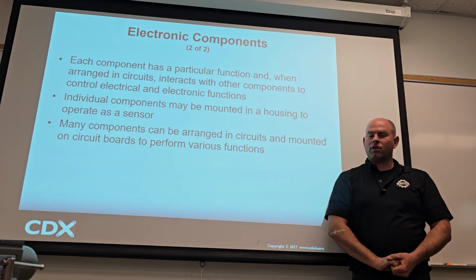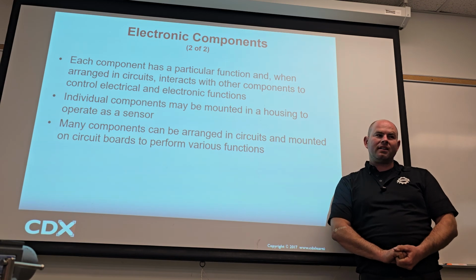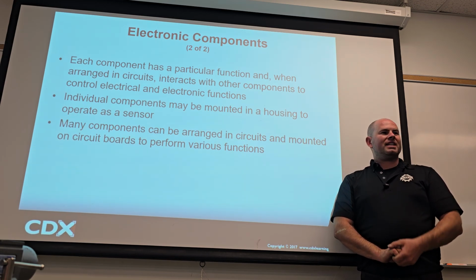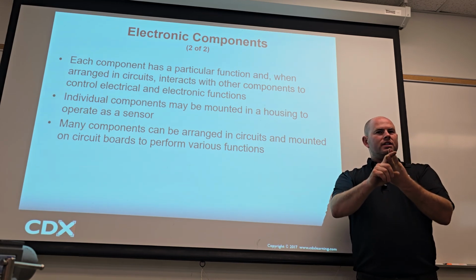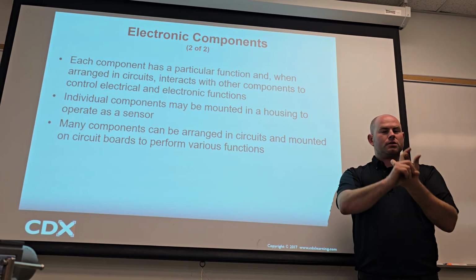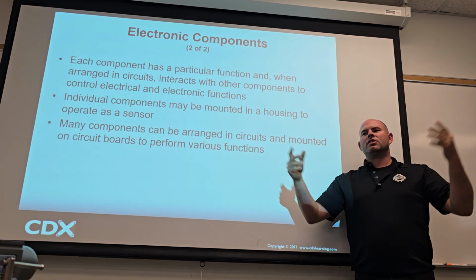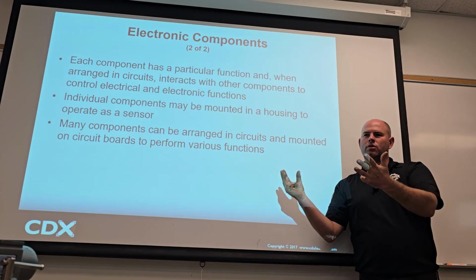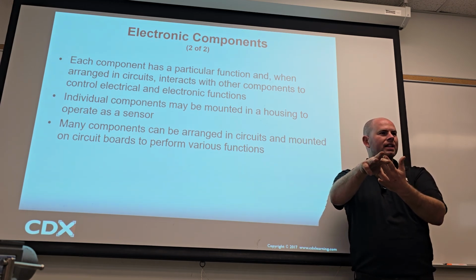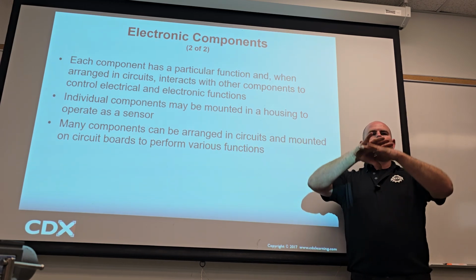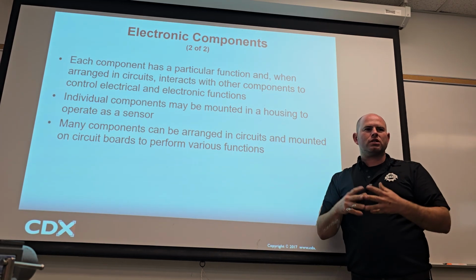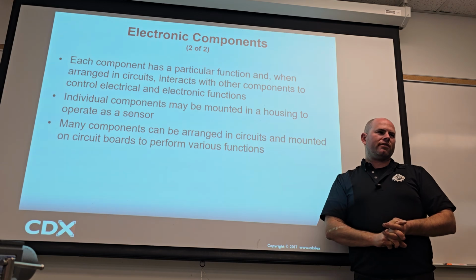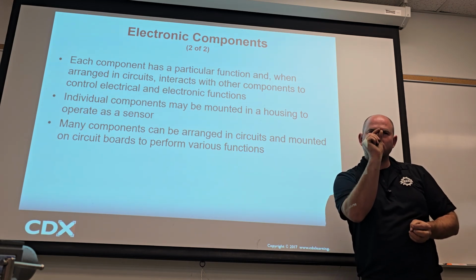Or you think if the whole ECM was offline, you wouldn't get that, would you? Exactly. It wouldn't control the spark. It wouldn't control the fuel. The injectors wouldn't pulse, the spark plugs wouldn't fire. I'm not even sure that the engine would crank because the computer generally controls the starter relay. If the whole computer is poof, you let the magic smoke out, none of those things are going to function. Not just one little tiny issue.